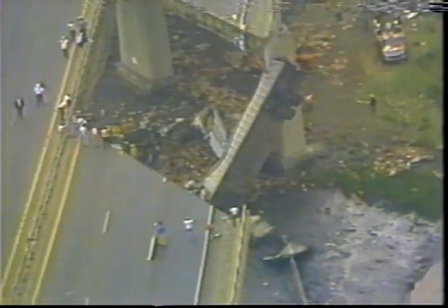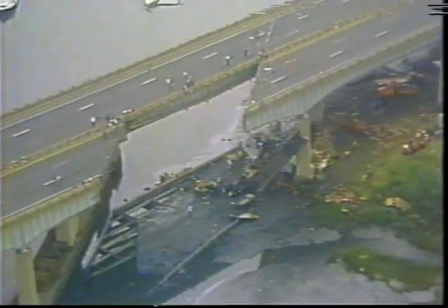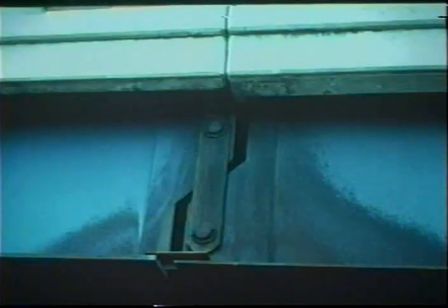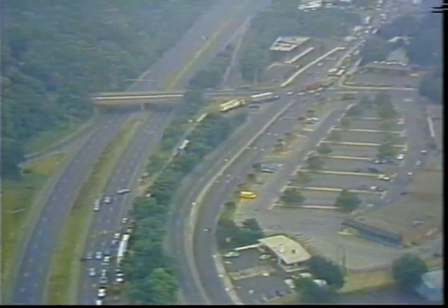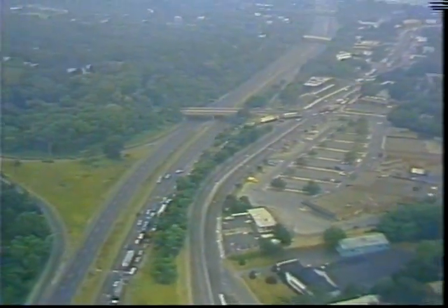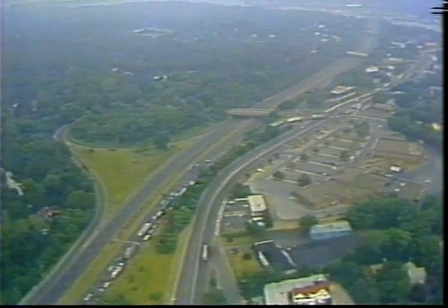The 1983 collapse of the Mianus River Bridge in Connecticut is an example of a failure involving a critical member. The failure of one of 4 pin and hanger assemblies supporting a suspended two-girder span caused the collapse of the span, killing 3 people and injuring 3 others. Such failures have resulted in public demand, legislation, and regulations requiring action by responsible local, state, and federal officials to increase the safety of these critical links in the roadway system.